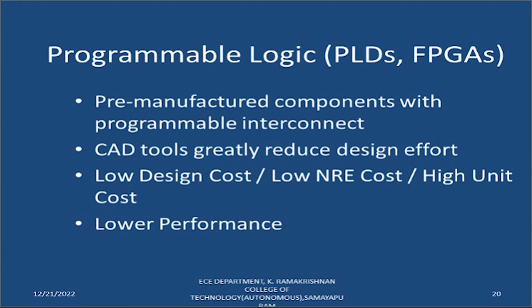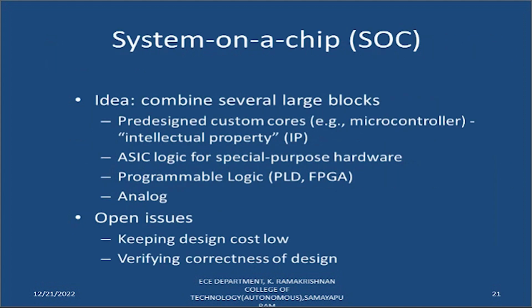Then if you take a programmable logic design, here we have pre-manufactured components with a programmable interconnect. So the CAD tools will greatly reduce the design effort, the design cost is very less, NRE cost is very less, and unit cost should be high. The performance of the programmable logic should be lower compared to that of the ASIC based design.